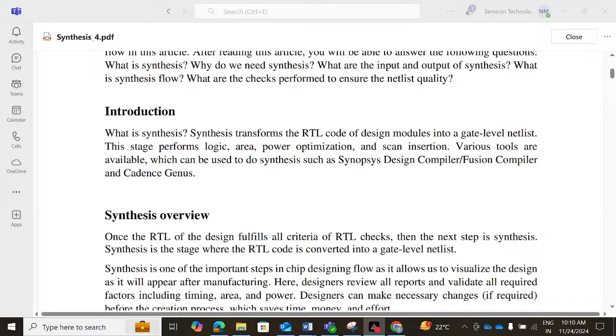Now, power optimization. The power optimization is always related to leakage power and dynamic power. So when we are doing the PG mesh, at that time we have to look into leakage power optimization. Similarly, when we are going through the flow, when we add cells during placement, CTS, routing, based on the cell placement and how many cells are getting added, at that time we have to make sure that the dynamic power is coming under control. Again, in dynamic power we have switching power and internal power, right? So the power optimization has to be taken care of. As we discussed in the previous synthesis in VLSI part 2 and part 1, we use the clock gating technique in order to reduce power.